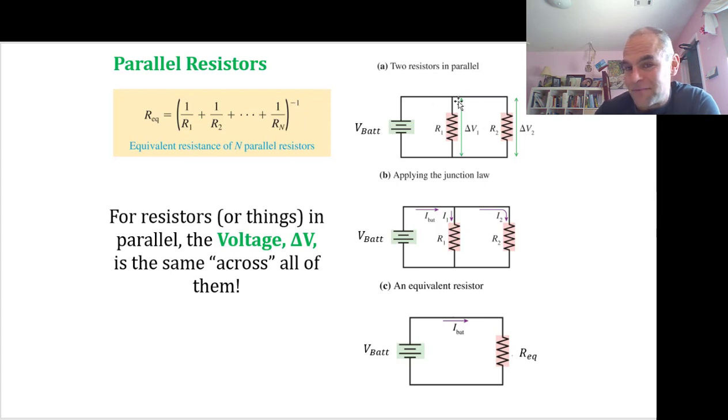If you take the inverse of that 1 over an ohm resistor, you're going to get that it's 1 ohm, which may seem funny. You have two 2-ohm resistors, you're putting them in parallel. Your result is a resistor that actually has a smaller value. That's always going to happen when you put resistors in parallel. We'll talk about why more, but this is an equation that will allow you to find what we call the equivalent resistance for two resistors that are put in parallel with one another.